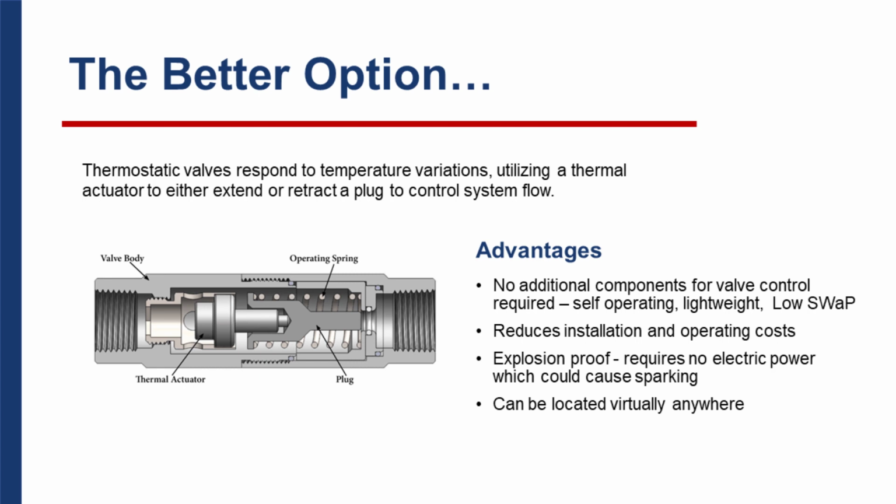So the better option, well, that would be a thermostatic valve. Responds to temperature variations, utilizing a thermal actuator to either extend or retract a plug to control system flow. The advantages here are no additional components for valve control required, self-operating, lightweight, and a low SWaP. Reduces installation and operating costs.